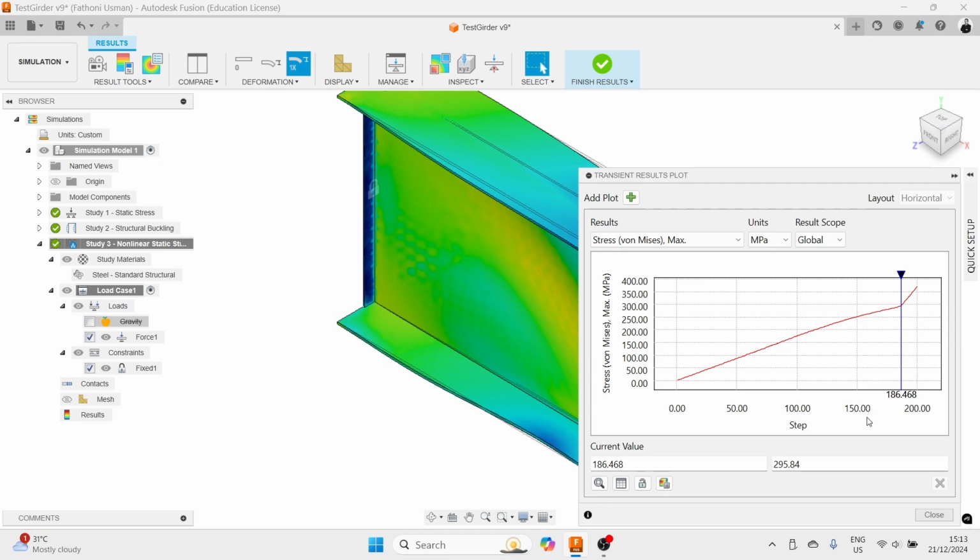So it is expected, almost the same value as by design, using buckling of plated structure. The value is 0.6, the C, which is the reduction factor for buckling. So buckling is 0.6 times 275. The difference is because of the different material strengths, and for sure in the design code the safety factor is also already embedded there.